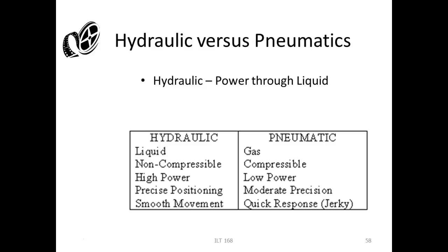But if we cause things to happen, so let's say we don't have enough fluid in our tank, and we start moving all our cylinders, and then the level drops down below the intake on the tank. What happens in your bathtub if it's not stopped up and you open the drain? A swirl will form and gas will come in. Then you will have this problem. Then you will have compressibility if you really get true gas bubbles dispersed within the liquid.